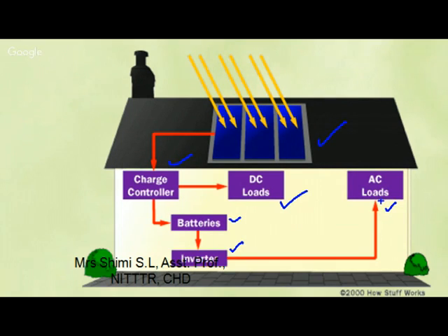So in an inverter, say you have a DC supply and you are converting it into an AC. First of all you get the DC, then you can reverse it. So this is nothing but your AC. But this AC is not fundamental, it is not sinusoidal, and it may affect your load. For such cases, we go for multi-level inverters. In multi-level inverters, there also it is DC only, but you will have something like steps here.